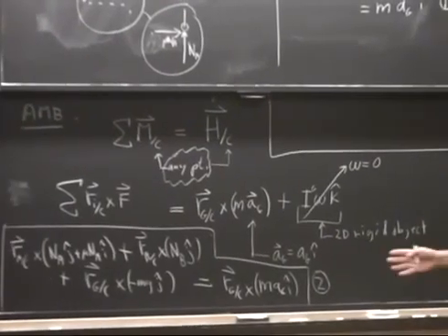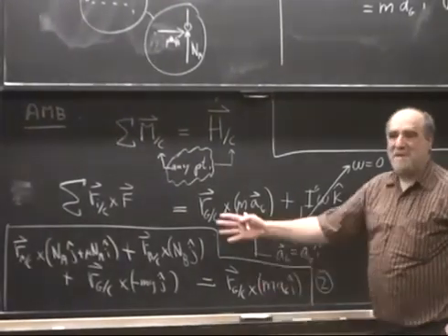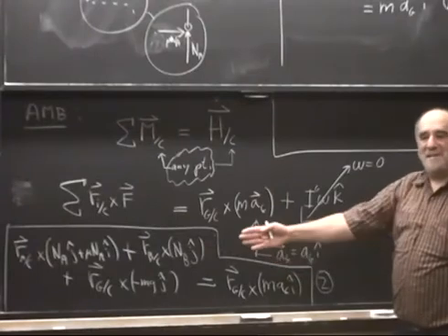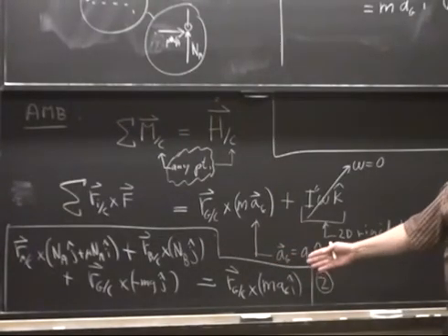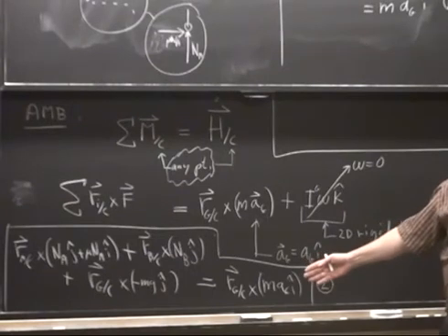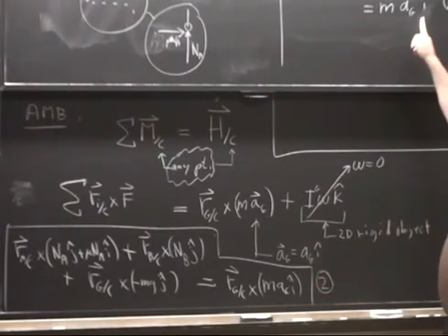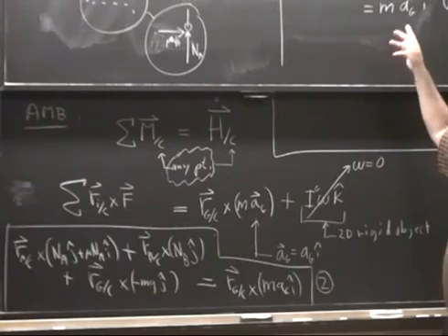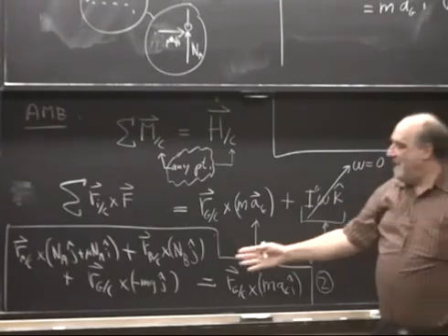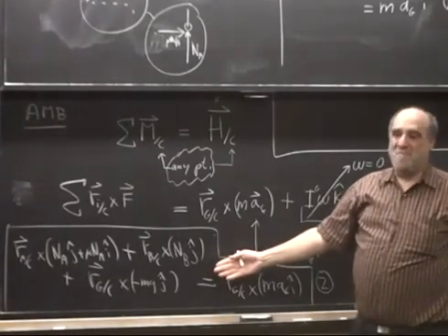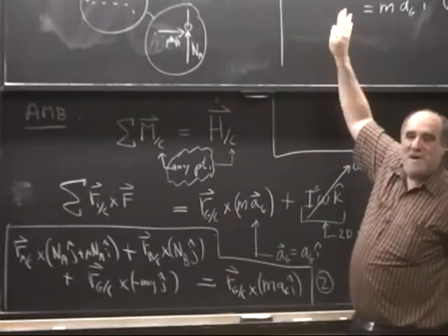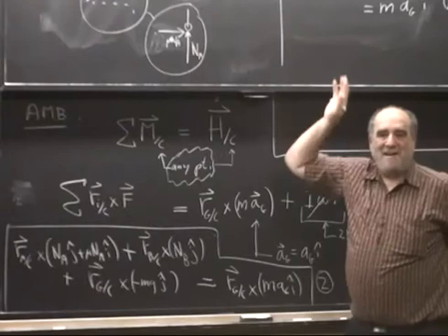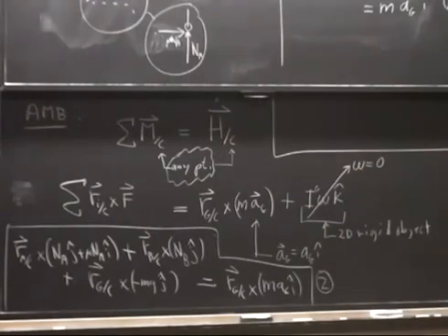Why is this vector equation just one equation? It's because every term is in the k direction. There's only one non-zero component in this vector equation, because it's all cross products of vectors in the plane. This is 2 equations. We could instead take angular momentum balance about 3 different points. That would give us 3 equations, and that would replace this one. No matter what you do for one free body diagram in a 2-dimensional problem, you can't get more than 3 independent equations.